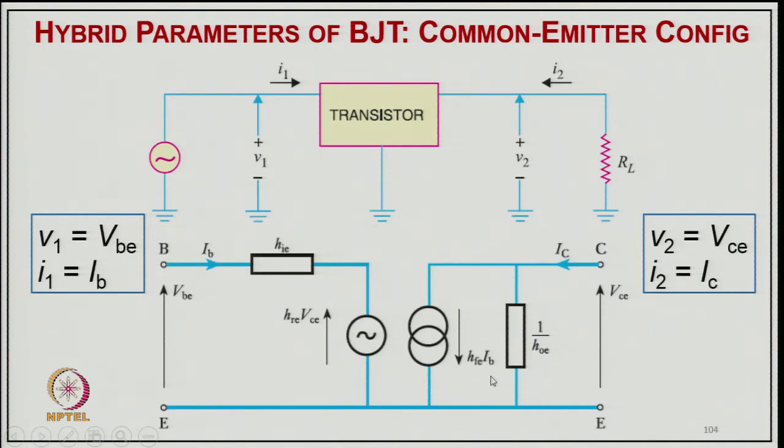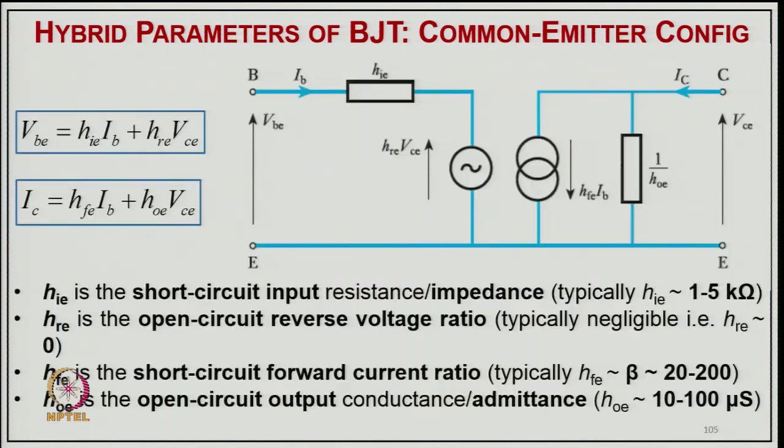So, this becomes what you can call a transistor amplifier or equivalent transistor, the H parameter equivalent circuit, where you have a dependent voltage source and a dependent current source. This dependent current source is in terms of input current, and this voltage source is dependent on output voltage, as we have looked into earlier with two-port parameters.